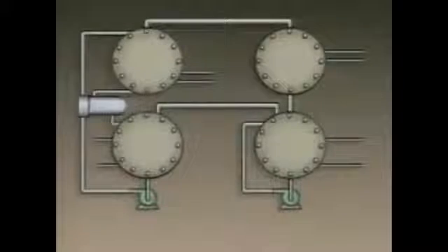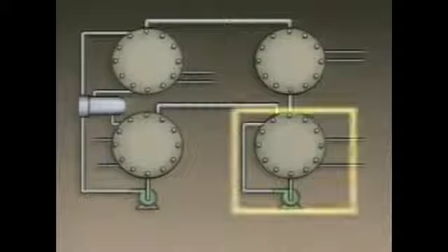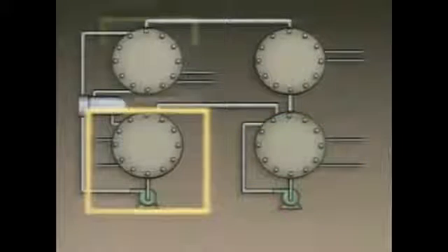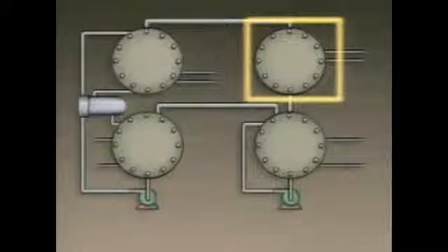Absorption refrigeration systems use chemicals called absorbents to control the pressure and temperature inside the system. A common application of a typical absorption refrigeration system is to cool water. The cooled or chilled water is then pumped to various components where it absorbs heat. We can look at an illustration of an absorption refrigeration system to see how it works. The example system consists of 4 main sections: an evaporator, an absorber, a generator, and a condenser.